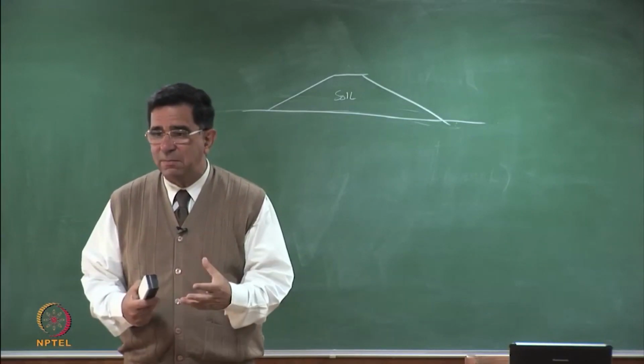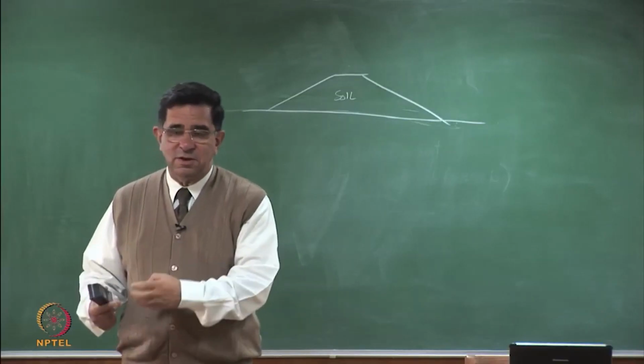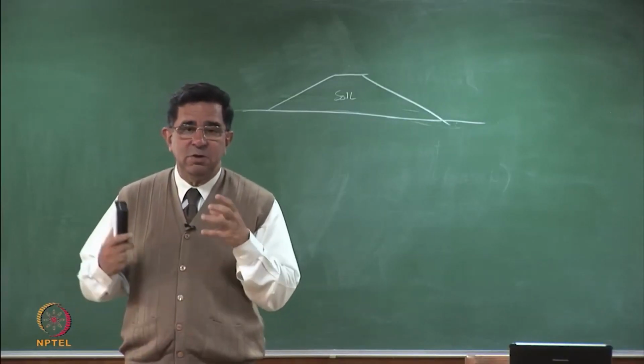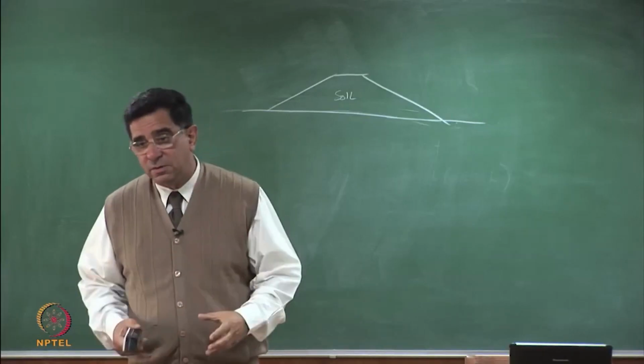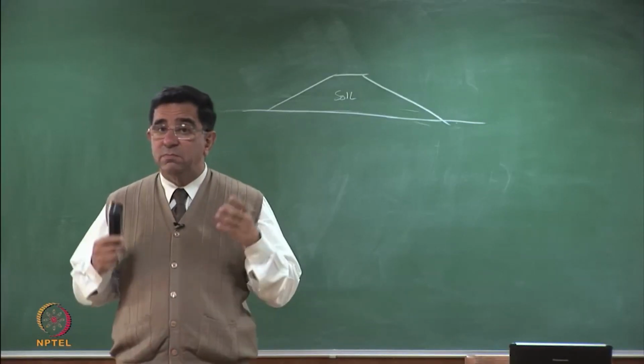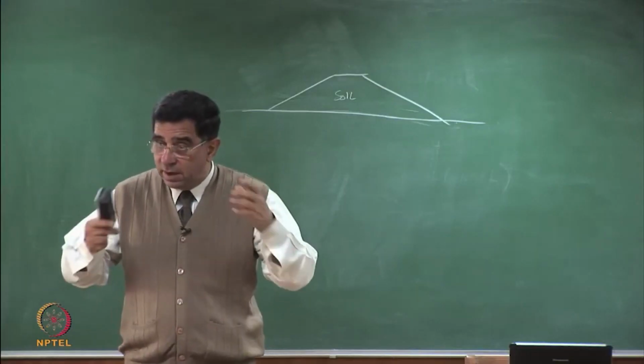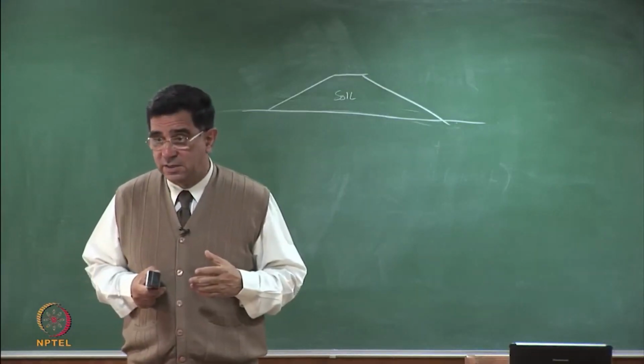Is it going to be wet sample? Is it going to be construction and demolition waste? Immediately it may not be possible to make a cylindrical sample. So good idea. Let's do large direct shear tests.